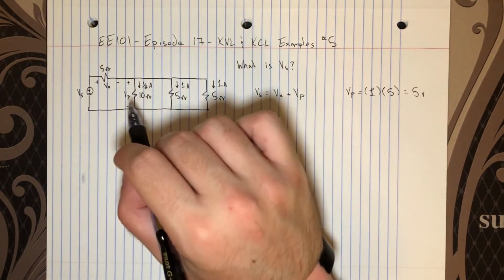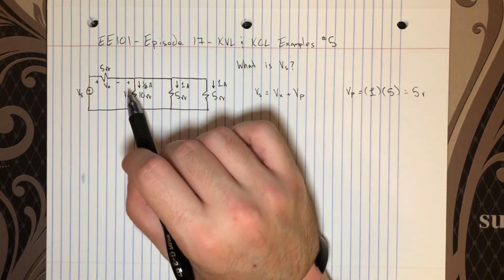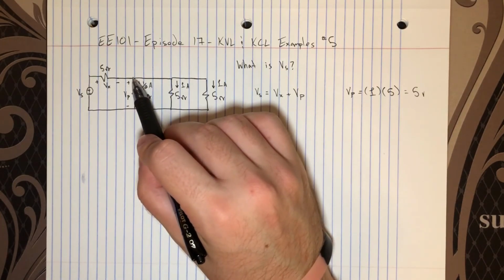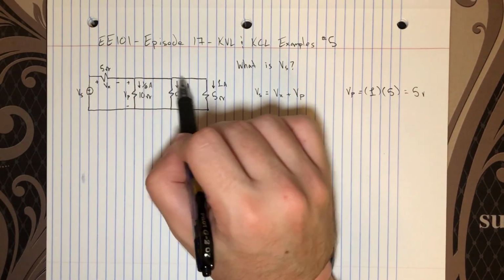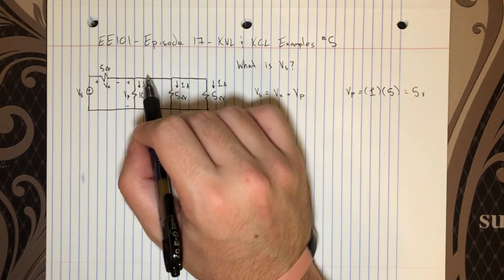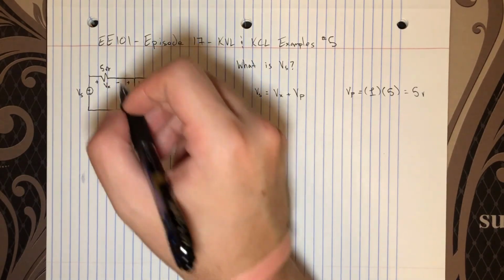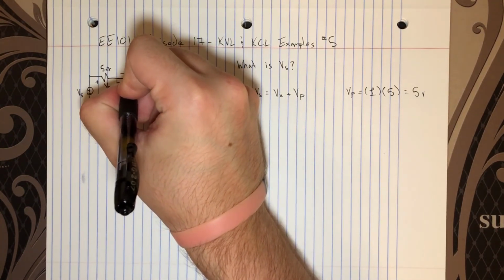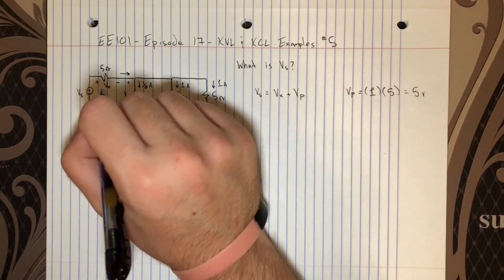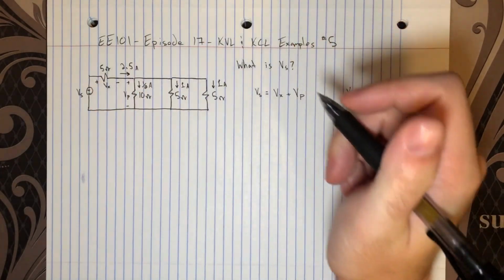And now we have all the information, and this KCL should be very obvious because we know that we have an amp, and another half amp all leaving this node. So there must be some equal current entering the node, and the only path left is the path from this resistor. So it's clear then that the current coming in this direction, traveling through this resistor, is 2.5 amps.